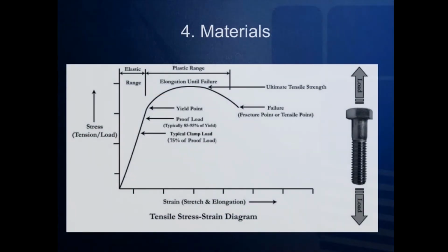To analyze the strength of fasteners, a stress-strain diagram is very helpful. This data is plotted by a machine that pulls onto a bolt and plots its change in length. This science centers on the principle that fasteners are elastic and act exactly like springs. When they are pulled, they elongate. However, when the force relaxes, they return back to their original length. Note that there comes a point where the bolt is pulled too far and its spring-like or elastic properties are damaged. This point is called the yield point. Once a bolt is pulled past its yield point, it has entered its plastic phase, in which it will not return back to its original length.